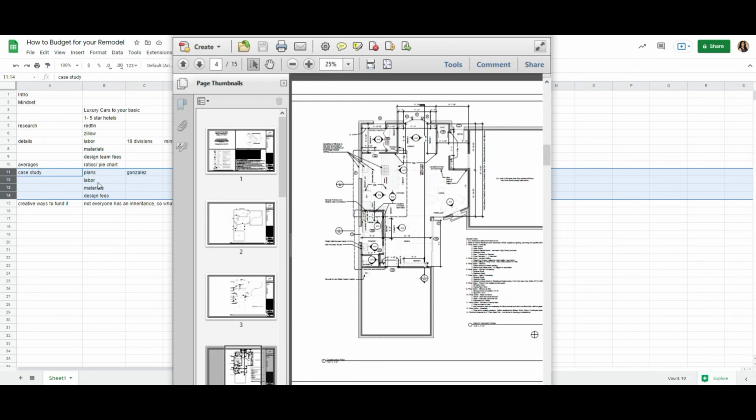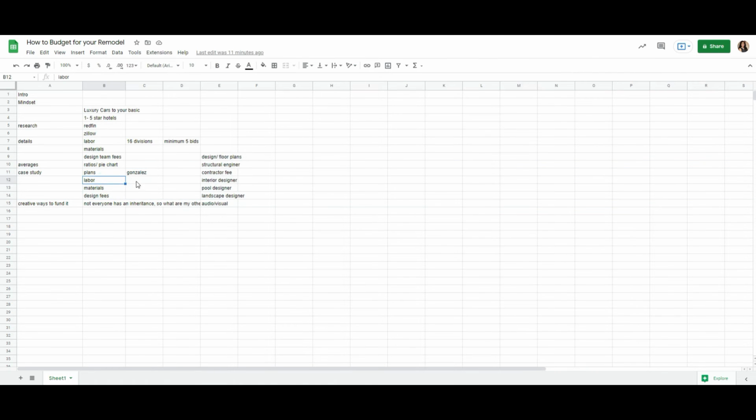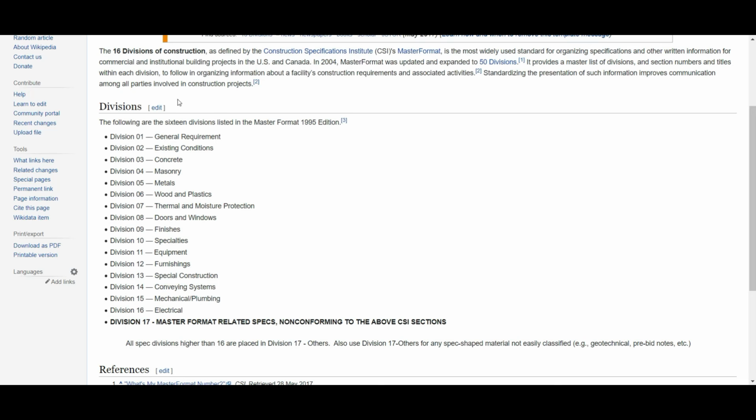Basically, you can see one set of floor plans, the same one, went to different contractors, and you can see how you come up with different numbers. And the more detailed the bid is, the better it is, just because you can see, did they follow this outline? What is the quantity? Can you go back to the floor plan and quantify it and double check it?